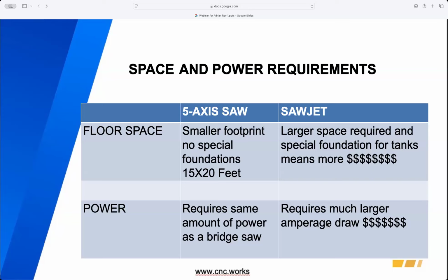Some of the people watching may not be familiar with the term intensifier pump. Can you say a little more about what it does? Yeah, the pump gets the water up to a very high pressure so it will cut through the granite. At that time, it also adds garnet through a line that mixes with the water, and that's what cuts, the garnet and the water. The power requirements are really high in that pump to get it up to pressure. They've come a long way since they first came out. They've done a lot to make the pumps better, but it still requires a lot more power than just a regular CNC saw.